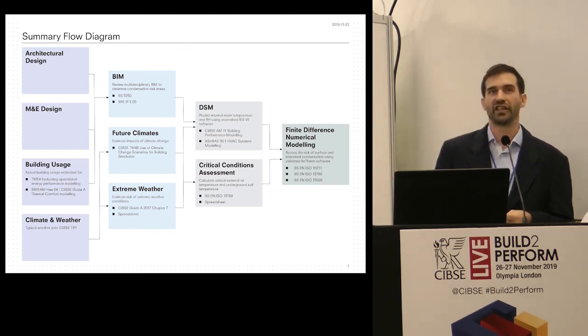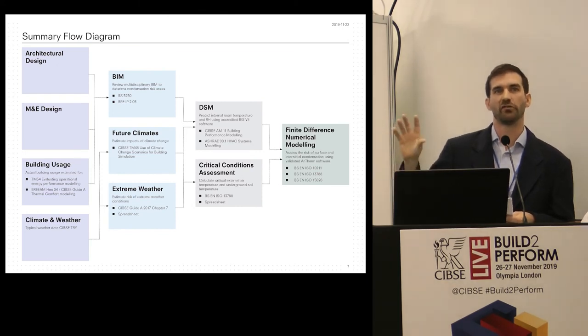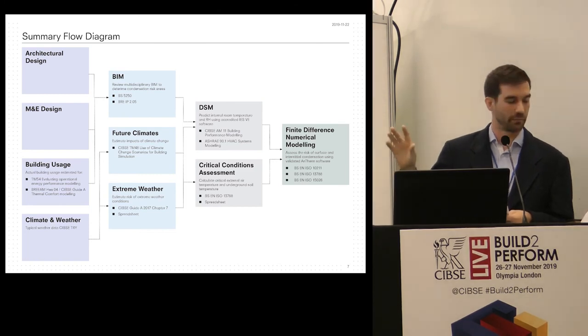In this particular project, we controlled condensation risk through a number of factors, one of which was more insulation in the foundations, the other was better control of plant rooms. The plant rooms were inside the internal envelope, so by identifying a risk using this, we were able to slightly modify the plant room design, which allowed us to eliminate risk in the design. Thank you very much.